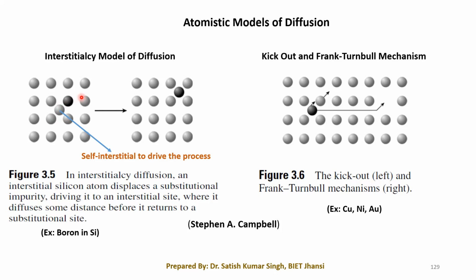Fine. So this way we have different models that explain the diffusion process. Whenever we are adding a certain type of dopant through the diffusion process, how these impurities are incorporated, how they enter into your material like silicon, how they get distributed, and then how they ultimately give you a certain number of extra charge carriers, whether electrons or holes.